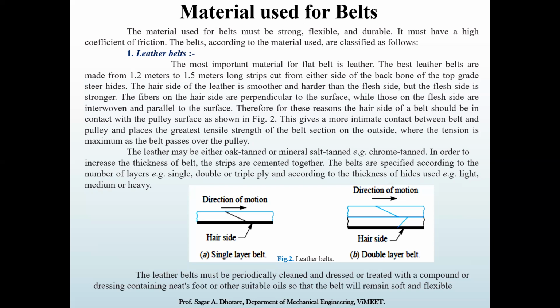When you consider the cross section of the belt, the inner fiber is under compressive stress and the outer fiber is under tension. So failure or crack propagation could occur on the outer side, and the outer side must be stronger than the inner side.